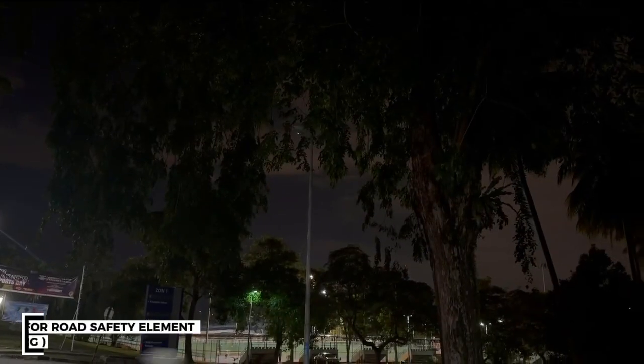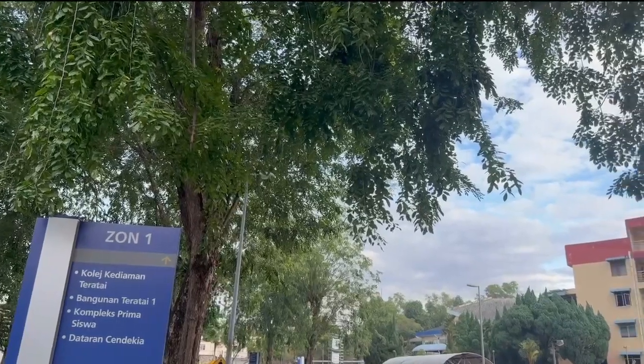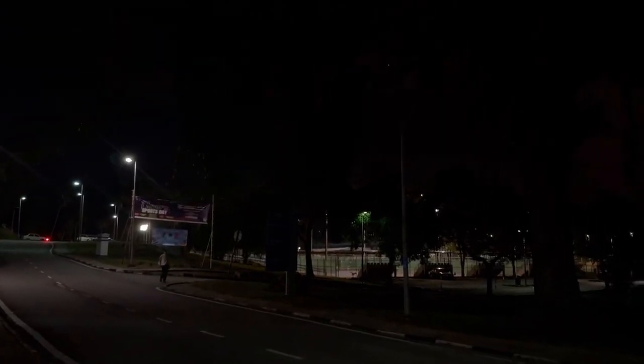In terms of street lighting, although lighting poles are installed, several lights are not functioning and some are partially obstructed by trees, especially near pedestrian walkways and crossing areas. Inadequate lighting increases accident risk at night. Therefore, repairing faulty lights and trimming vegetation is recommended to ensure adequate illumination.